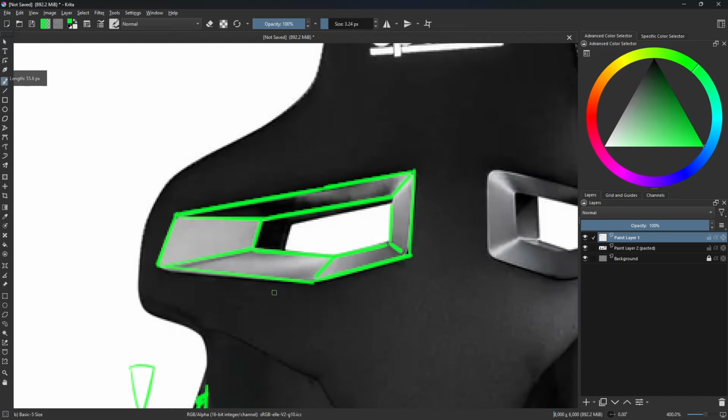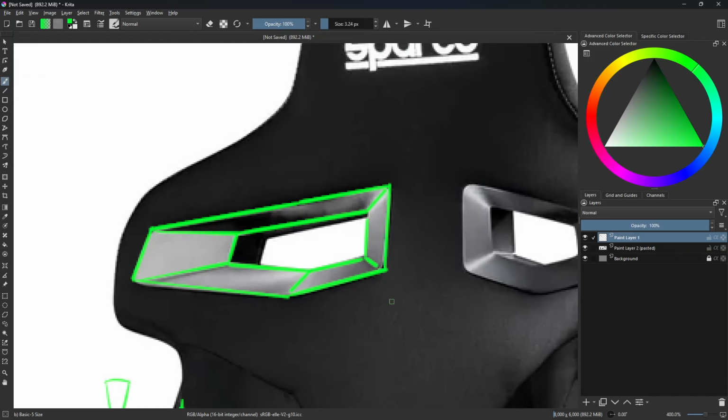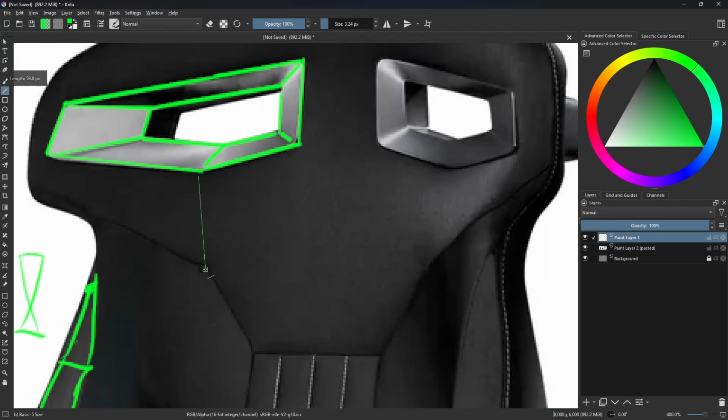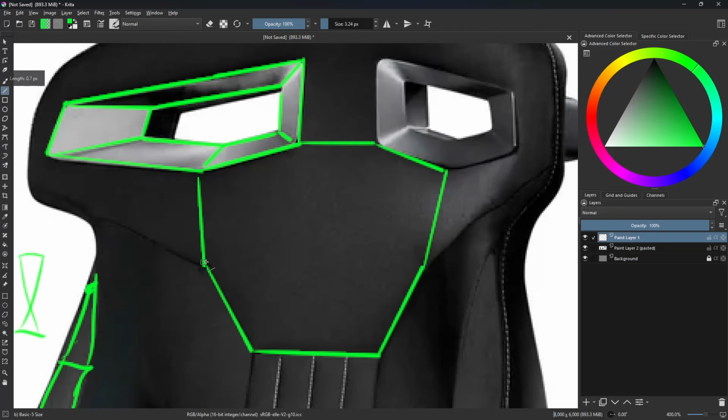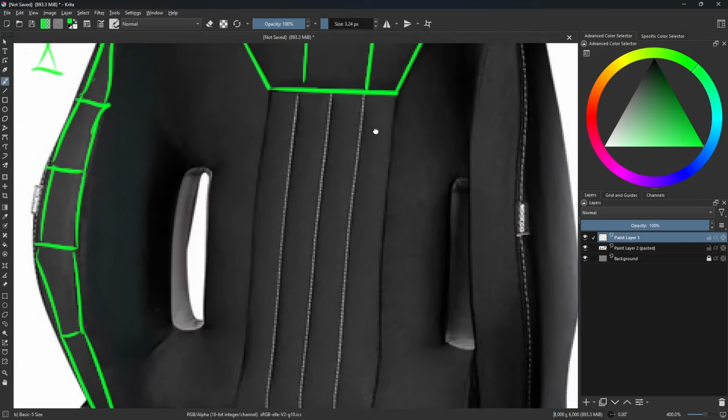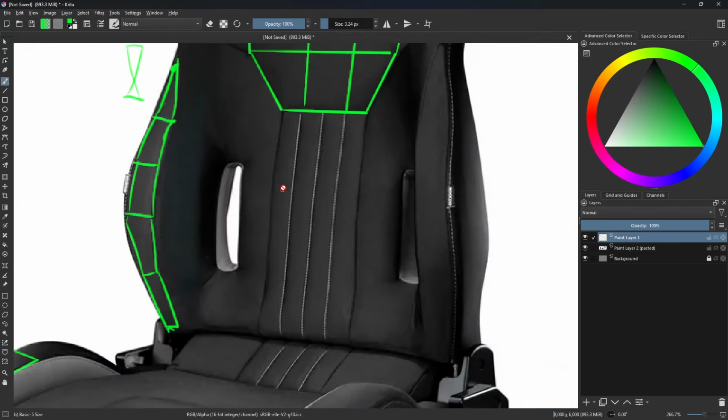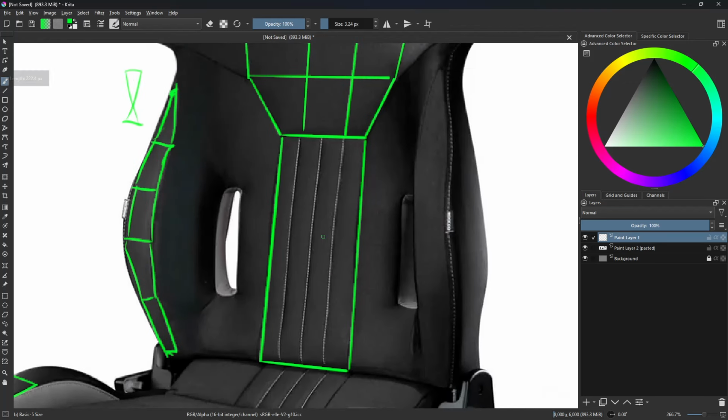Okay. That's the kind of form you're creating. Remember, shapes are 2D, forms are 3D. And even if there's not an edge for it, look for those little areas where they're lining up with each other. You're creating a big n-gon, something like this, right? Well, you can convert n-gons into quads. You see where I'm going with this? They're very simple, usually, the topology anyways. This is a big rectangular plane, basically. Later on, you add the details, the stitching and all that. You might break this up even more, who knows? But you start with the basic stuff first.